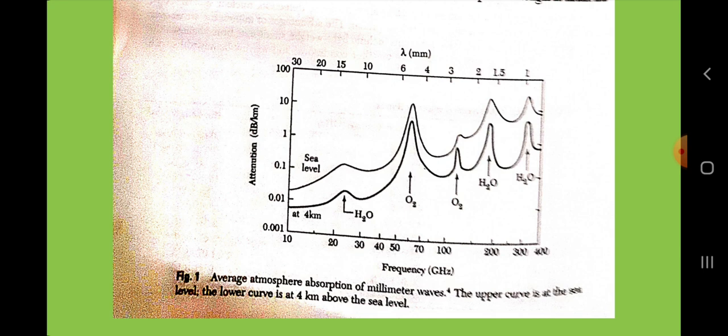Planar transmission lines are the mainstay of modern microwave circuit technology. Such lines consist of one or more flat conductors on a thin dielectric substrate with a ground surface. The figure shows several basic types of planar transmission lines: microstrip, coplanar waveguide CPW, stripline, and suspended substrate stripline SSSL. Microstrip is the most common type of transmission line. The coplanar waveguide is somewhat lossier, that is, loss in signal propagation is larger, but it minimizes the parasitic inductance of ground connections.